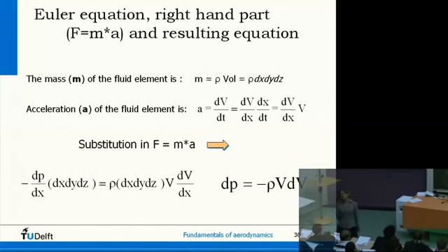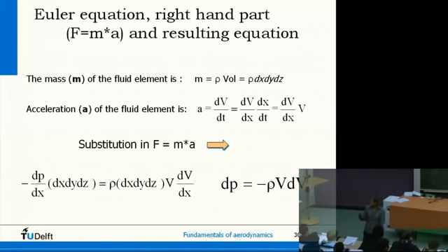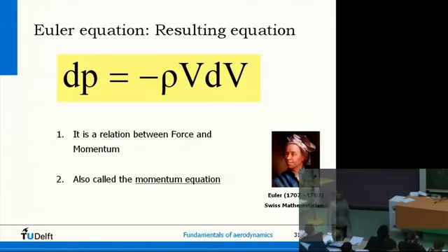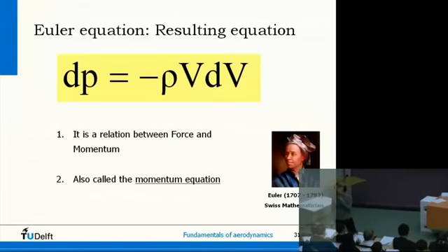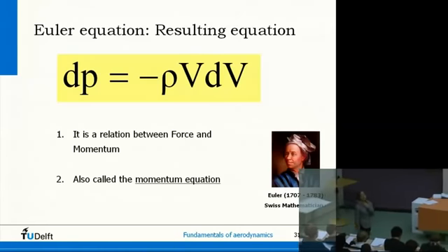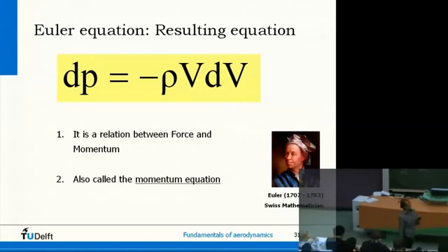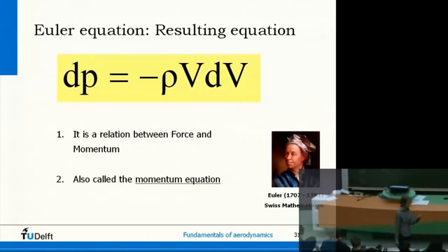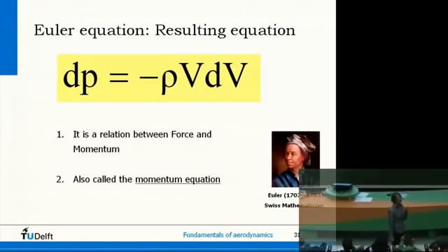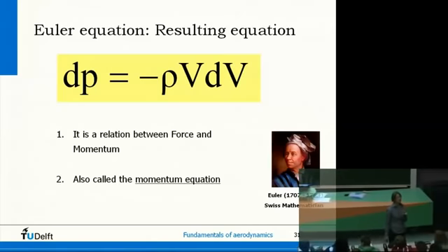So we'll now do the derivation. This is still valid. The differential form is valid for compressible and incompressible flows. We will now integrate it for incompressible flows. Please remember, and also you should be able to derive this. We might ask you at the exam, please derive the Bernoulli equation, because it's important to be aware of what you neglect, gravity, friction. It's not too tough. And then you see where your relation actually comes from.